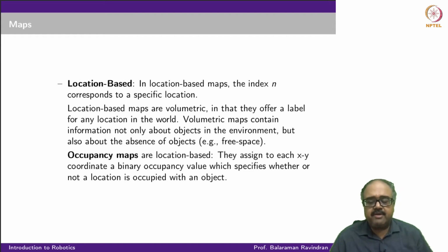You can even store it as a bitmap of 0s and 1s, and therefore sometimes even for large spaces you can have a compact occupancy grid or occupancy map. When you are operating in a continuous space, we typically don't look at each continuous xy coordinate value for occupancy maps. What we do is make a grid space.